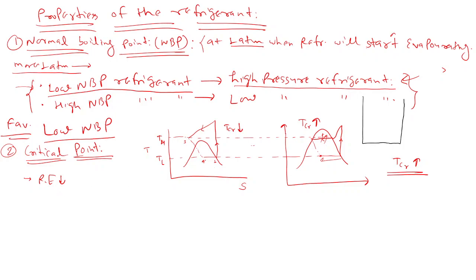Now the second part: you fix the refrigeration capacity. Like you have decided 10 TR, 10 ton of refrigeration, is your requirement. So 10 would be fixed. It depends on m dot, the mass flow rate of refrigerant, and the refrigeration effect. Refrigeration effect is H1 minus H4 only.